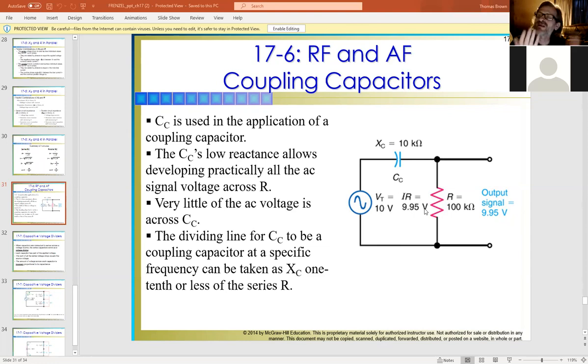So because of that factor, the higher we make the resistor the better, but you have to be careful, because at a certain point you make an unbalanced circuit if the difference in impedance is too great between the two components. If one is very much larger, it kind of negates the smaller one. But if you keep it within a range, like in this case a 10 times range, you're still able to get the effects of the capacitor without dealing with so much of the negative aspects of it.